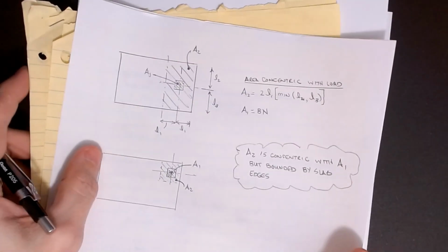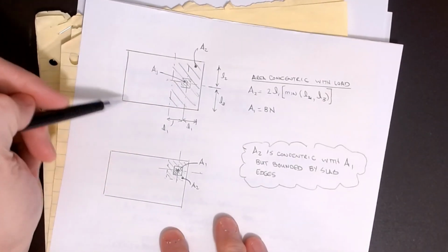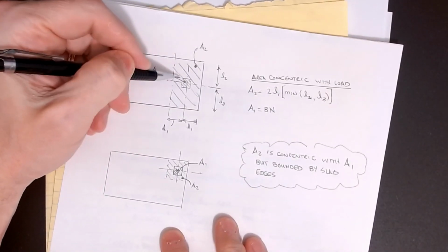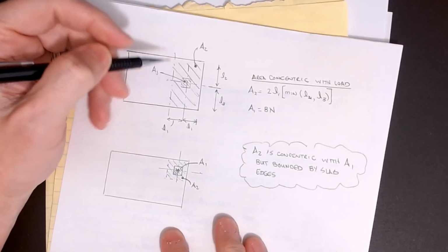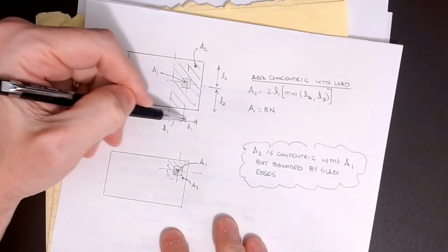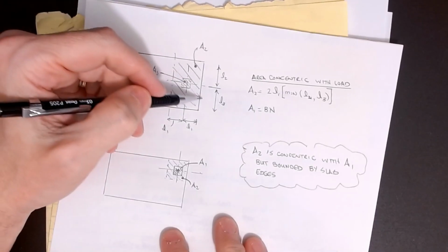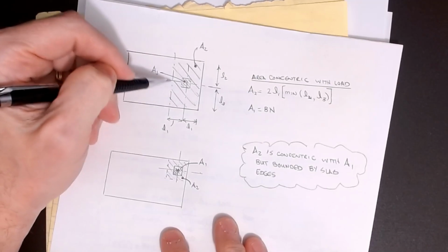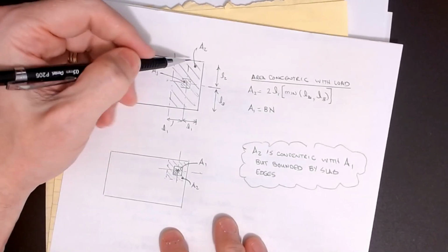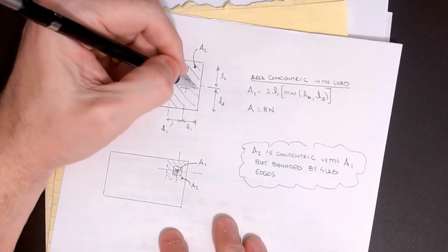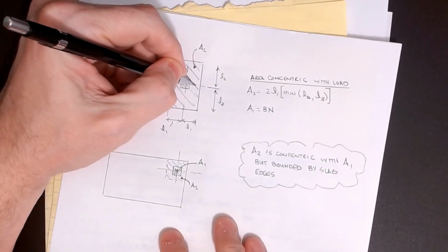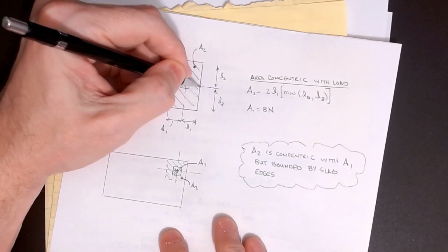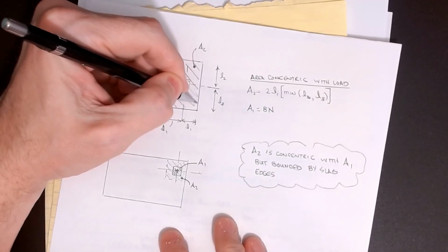All right, now I know that picture is a little confusing. Let me show you another version of it. So let's consider a big slab here, and I'm not going to draw it as an I-beam. I'm just going to draw your column area that's here, and it's located a distance of L1 from one edge. Well, the concentric width associated with that is another L1 this way. So this big shaded region here is what I'm calling A2. And then relative to the center of the column, I have two possible dimensions, an L2 up here and an L3 here.